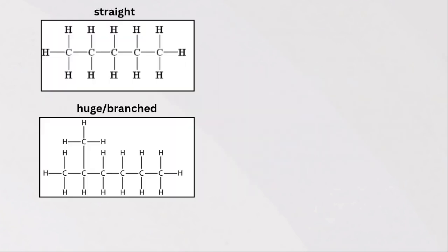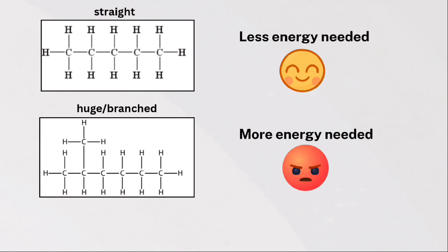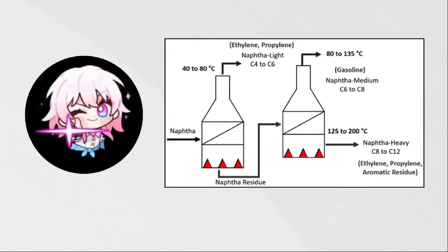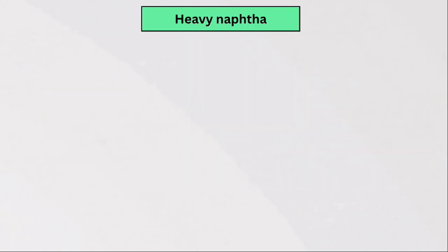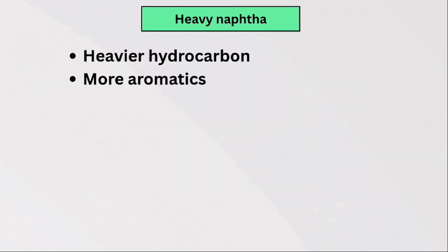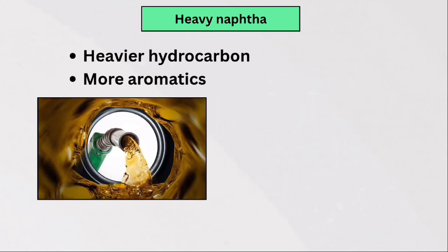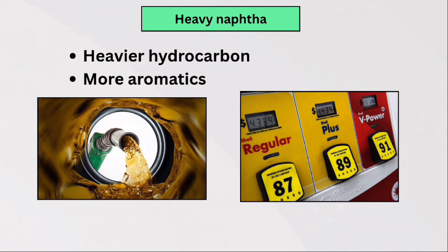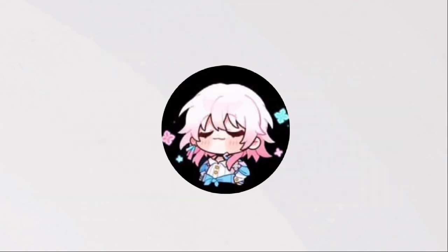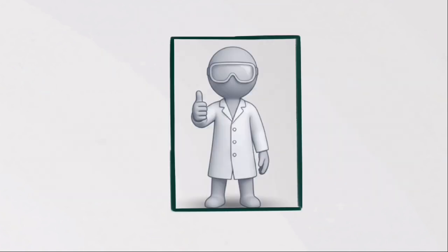Because lighter paraffins crack more easily, making light naphtha suitable for producing ethylene and propylene. And the heavy naphtha? Heavy naphtha contains heavier hydrocarbons and more aromatics, so it is usually used for catalytic reforming, generating BTX and gasoline production by pushing higher octane value. Then, I think light naphtha is more suitable for producing IPA, right? Exactly! On to the next process.